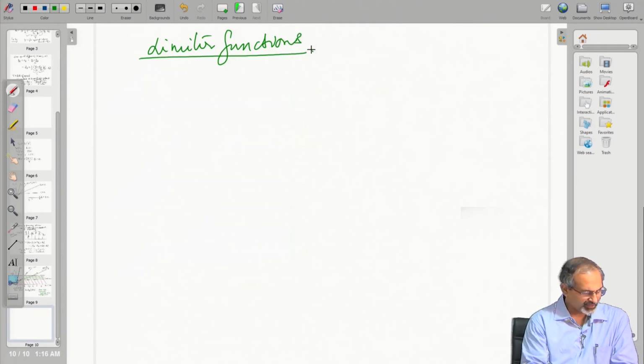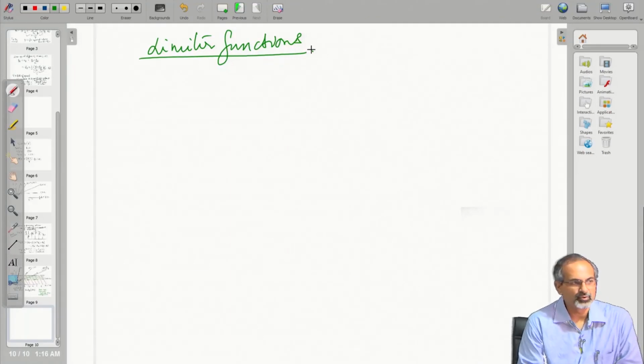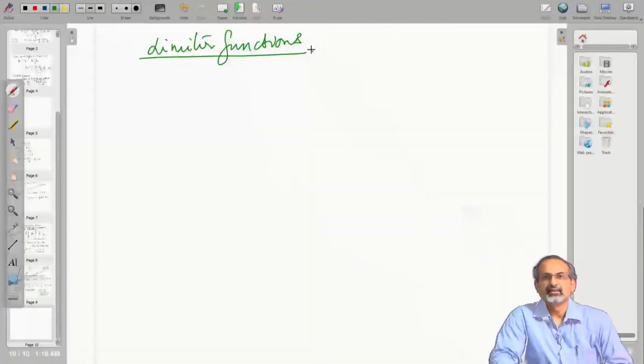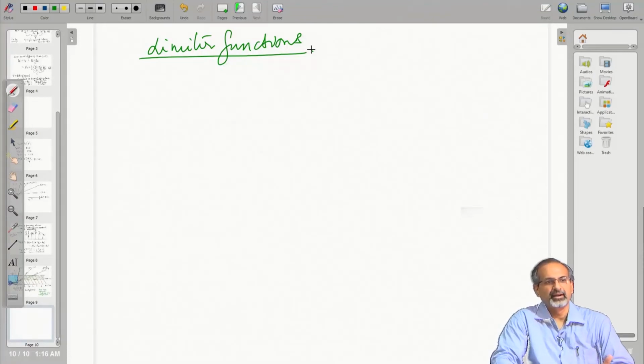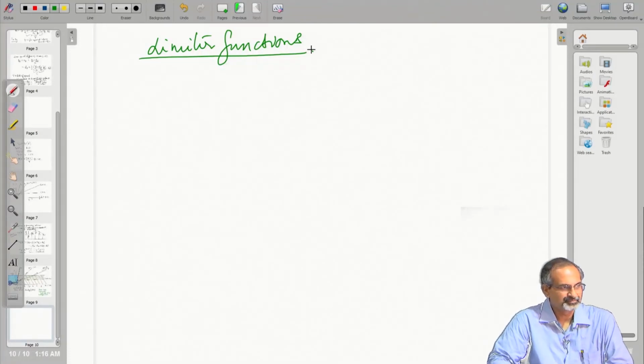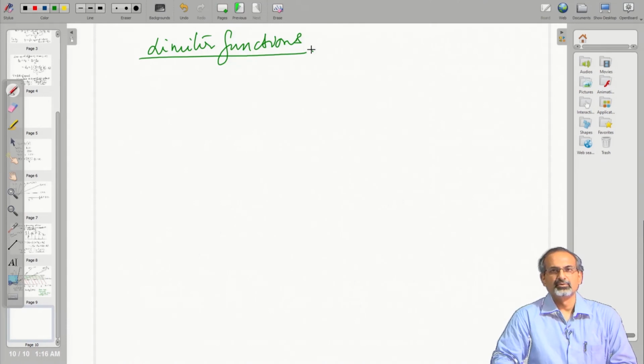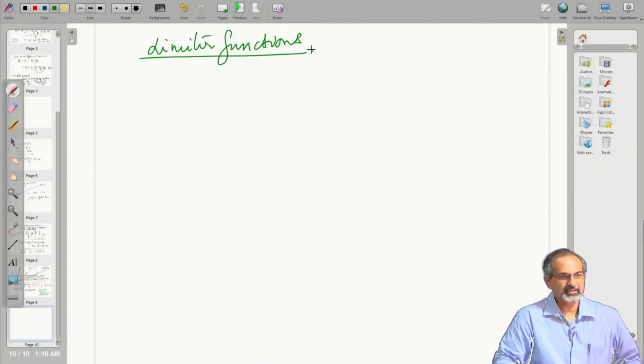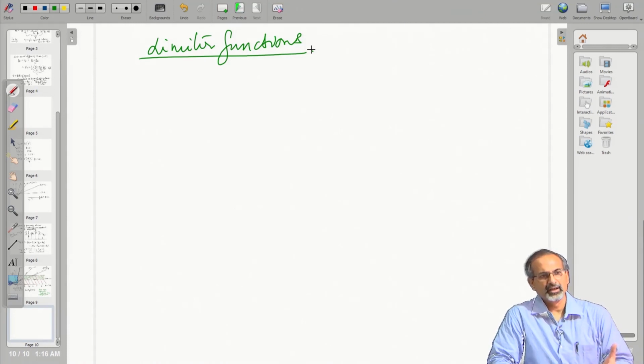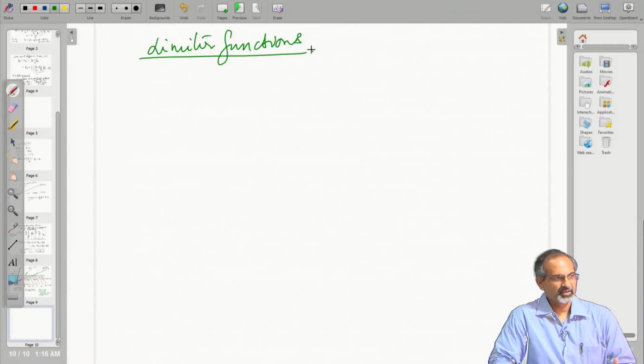Some of the functions are smooth, while some of them are piecewise linear. Piecewise linear functions we have seen earlier, for example, the hybrid scheme was a piecewise linear scheme. Again, in this TVD world, we have piecewise linear schemes. Again, we have smooth functions. For example, in power law, we saw a smooth function.